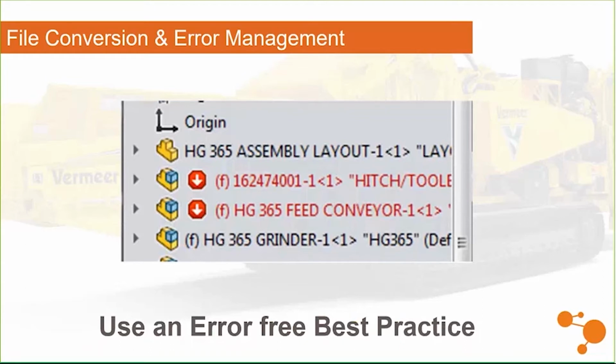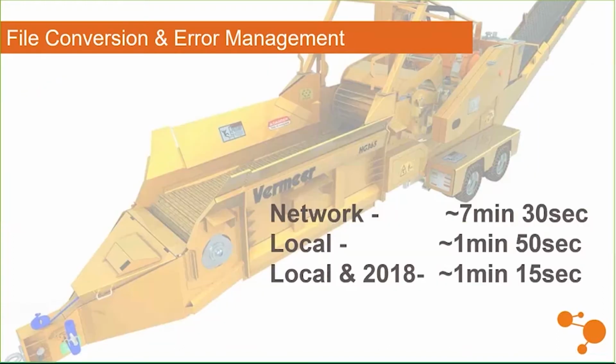The same is true for errors, right? So we don't really have a good baseline of what kind of gain you can get here, but errors in your assemblies and parts cause delays. SolidWorks is trying to figure out if it can fix those issues while it's opening the files, and when it can't, then it stays as an error after it comes open. And so it's just unnecessary thinking time, really, resolution time that SolidWorks isn't going to be able to do if you don't resolve those errors: fix your mate errors, fix your feature errors, or suppress those items if they're not needed.